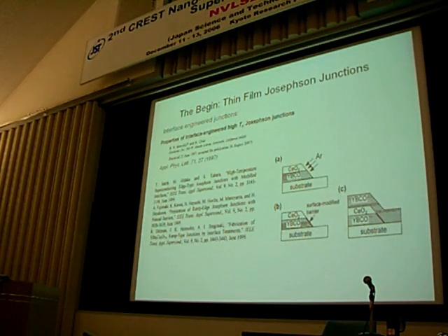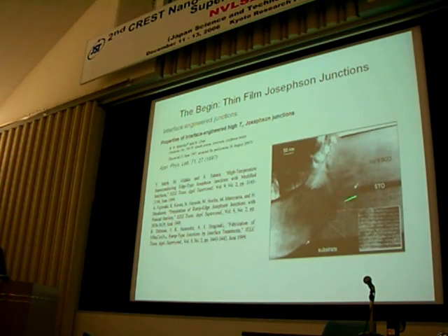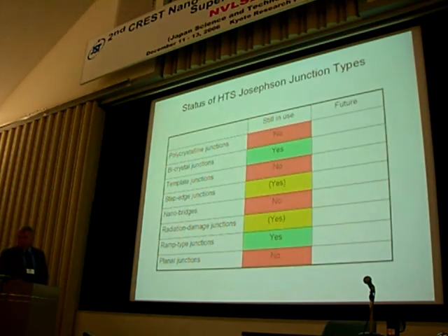In 1999, it was in Japan as well as in Europe a hot topic, because one thought that the reproducibility would become much better. You see here the preparation step with the argon ion beam. It turned out that the reproducibility was very similar to the epitaxial barrier ones. So there must be something else going on. You see here a TEM section, in this case from the group in Munich in Germany. It's very difficult to identify where the barrier actually is, so it's not easy to study that system.